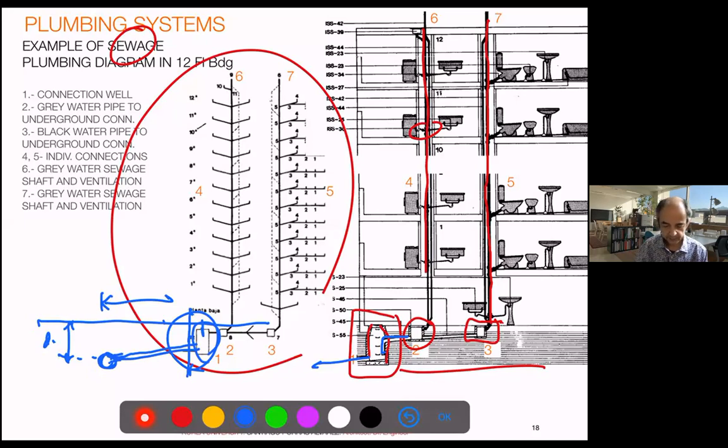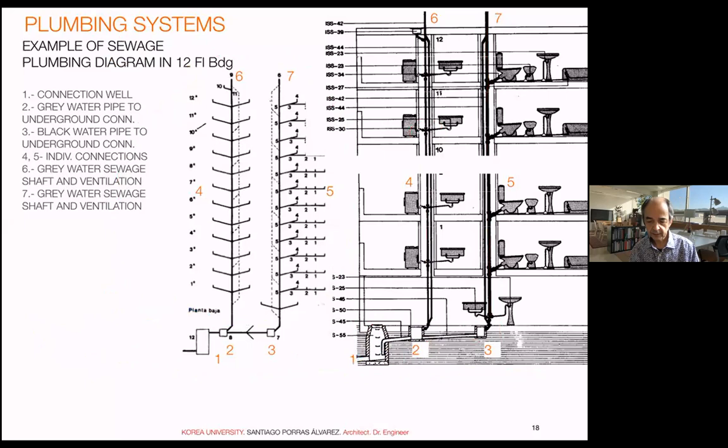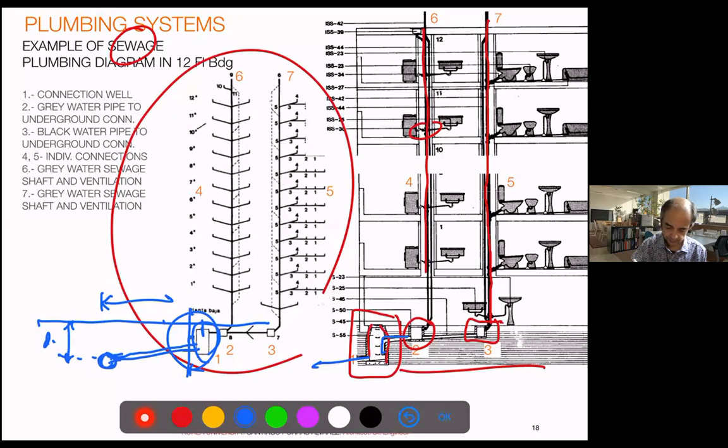There is one interesting element which you will see. Let's erase everything. You see that the vertical pipes have this dotted line in parallel, connected every other floor. Same for the kitchens, and they connect again, and then they go to the top. So those pipes have a ventilation, right? And you have a parallel element which helps that ventilation. That's important. And this ventilation is usually very smelly. It goes to the sewage.